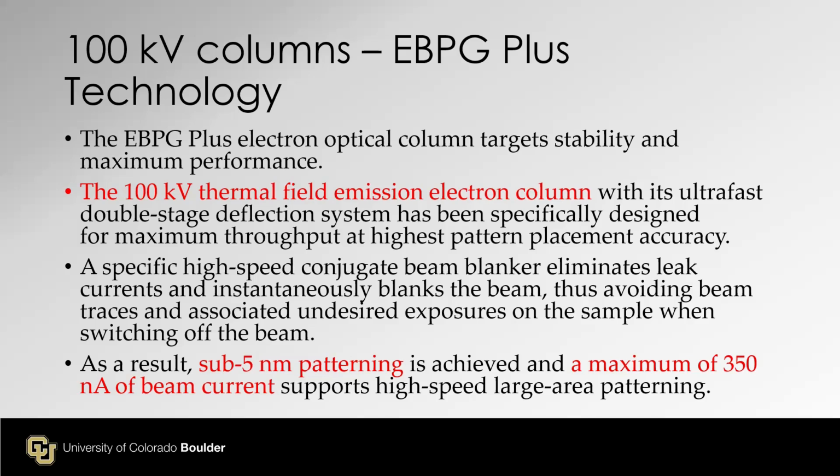Yes, we need to have field emission for a better, smaller beam size. And also 100 kV: the higher the kV, generally speaking, the smaller you can make the spot size. That's good. However, the important part of the hardware of an E-beam direct writer is not so much about 100 kV. Well, it's still important, but the column needs to be stable.